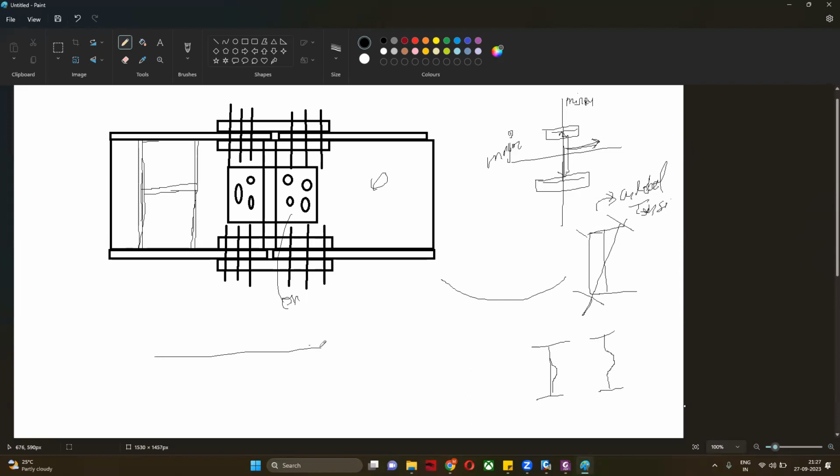In lateral torsional buckling, we need to consider the effective length, from one point to the other point. If you do not provide anything, our effective length becomes bearing center to bearing center. That will be 36 meter. But if you are providing any bracing or any stiffener, our effective length changes to the distance between two stiffeners, or from end to one stiffener, whichever is the highest.